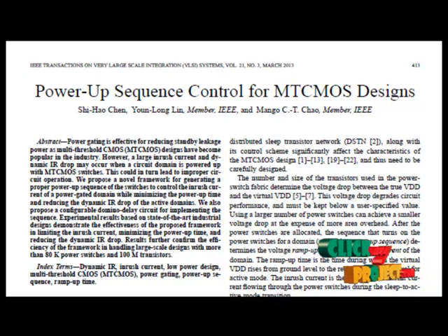One of the main causes of static power loss is leakage currents. There are a wide array of techniques designed to reduce leakage currents. The most effective techniques involve power gating circuits, essentially cutting off the pull-up network and pull-down network from one or both power rails during idle or sleep periods. During active periods, the circuit is reconnected to the power rails in a process known as wake-up or power-up.